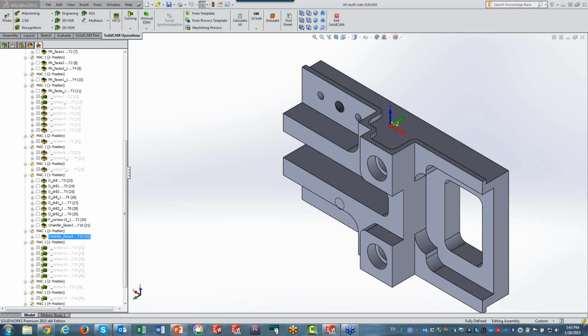Okay, I see there's a question here. Does AFRM work if there is a corner fillet between the walls and the floor? Well, does it work if you have a tool with a corner radius? I think I showed exactly how it worked over there. You probably asked the question before I actually showed how I did it with the corner radius at the floor. If you have a wall radius, it works just like a regular end mill on the wall itself. And the floor radius, it works exactly the way I showed it.